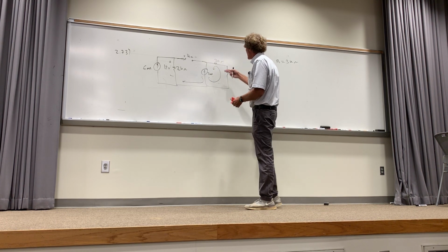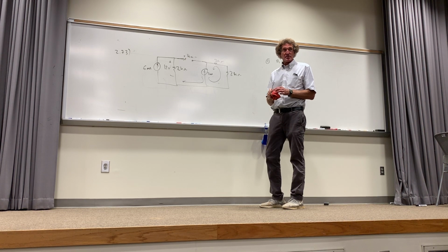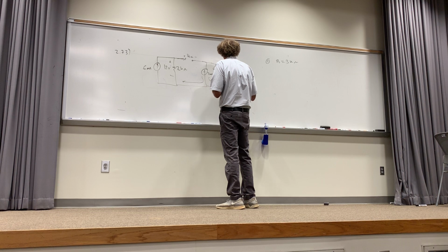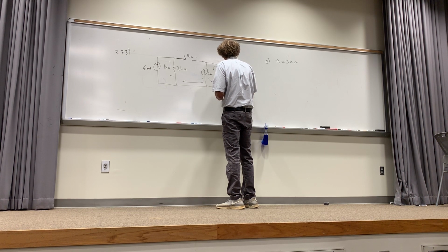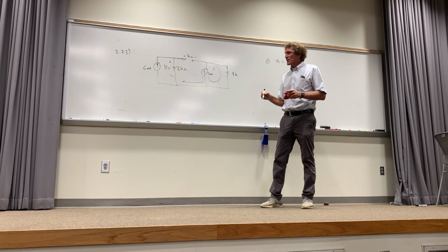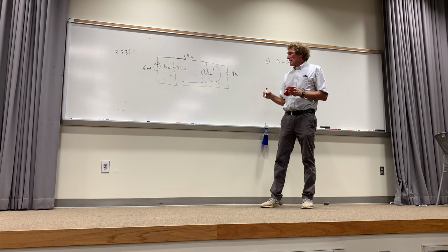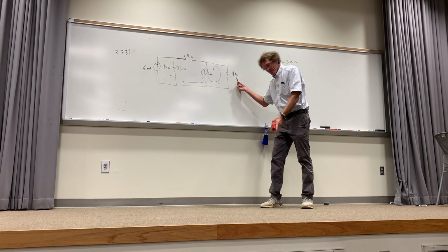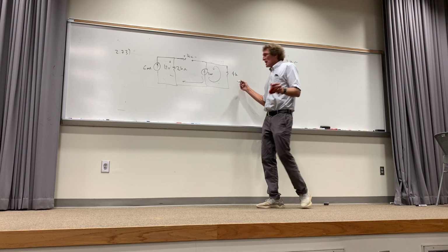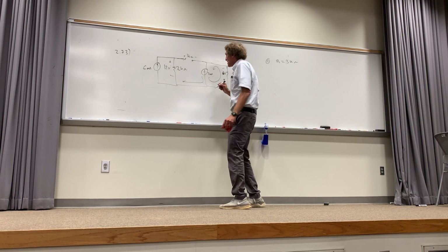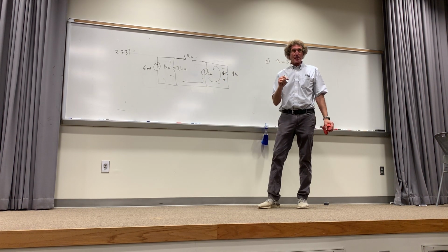If it's all flowing that way, can't we put these two in series? I'm going to do that too. So I'm going to go ahead and just make this 4K, right? Now, for the record, what is the voltage across that 4K with polarity? I got 2 milliamps flowing through 4K is 8 volts, right? 8 volts. And positive current enters the positive terminal. So the polarity would be plus to minus 8 volts. Do you all agree with me?